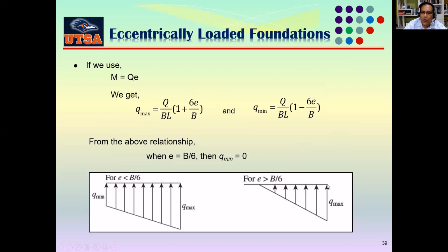So in that situation, if this is the width of the foundation, then you can see only a small part, not a small part, but a fraction of that part from here to here, like we call that one B prime, multiplied by the L. That's actually the effective area where the load is going to be distributed.